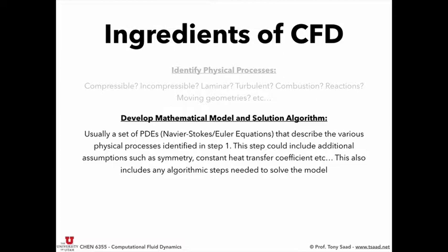If you have fluid structure interaction, you have to figure out how you pass the forces from the fluid to the solid and how to solve what's going on inside the solid. But this step also involves a solution algorithm, because your equations may be formulated correctly, but there may still be a step that's missing. I'll show you in a second, you could have 4 equations and 4 unknowns, but one of the unknowns doesn't have an equation. So how do you find that unknown? You have to tweak your equations a little bit so that they are readily available to be implemented on a computer.